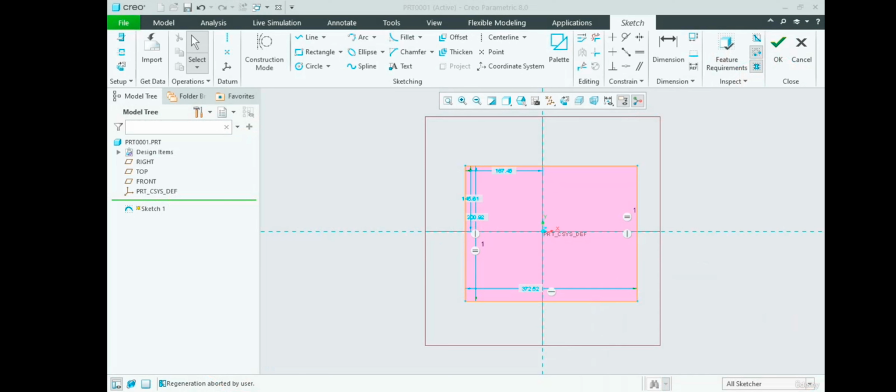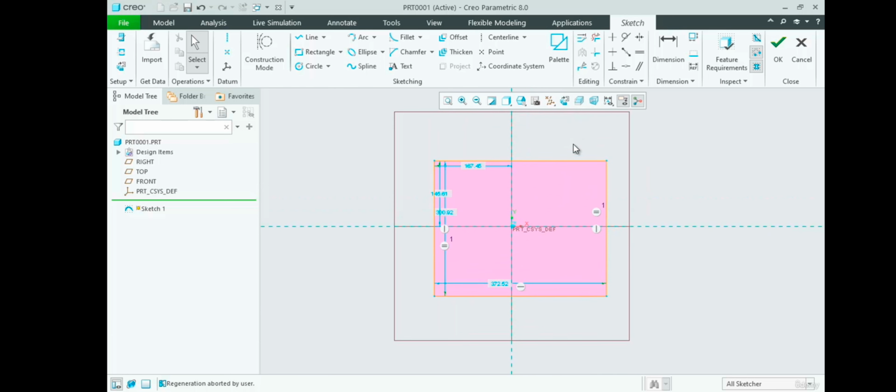In this lecture, we are going to discuss over-constrained and conflicting constraint geometry. Here you can see I have a rectangle. Now, in this rectangle, suppose I use some other constraints, maybe this and this, both are parallel. Suppose I say I will make this line perpendicular to this line, which is not possible. So let us give a constraint and see what happens.